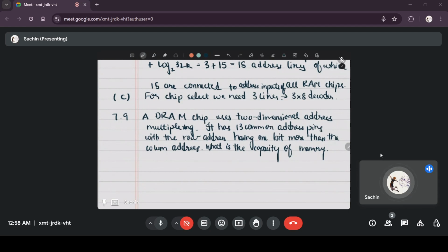So there is a select line for the row address and a select line for the column address. First you will select the row address and load the row address onto the address bus, and that will select which row you want to read or write to.